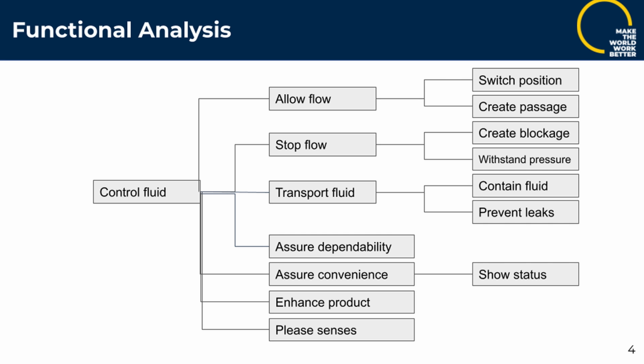We did a functional analysis of a valve, and the primary function of a valve is to control fluid. As you move to the right, we have more functives, and the final functives that we came up with were switch position, create passage, create blockage, withstand pressure, control fluid, and prevent leaks. We also came up with show status to assure convenience.